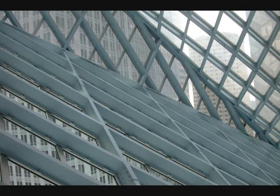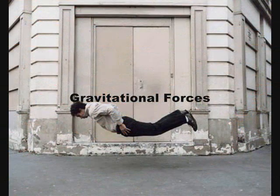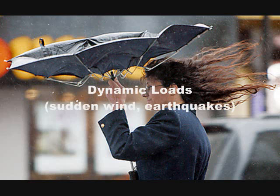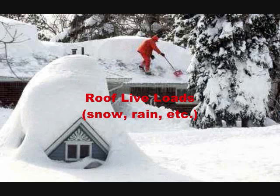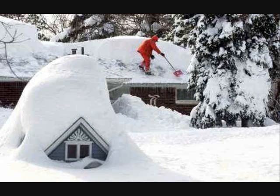As we mentioned before, nodes are where all the forces are redistributed. And there are many forces acting on the buildings, so nodes have a lot of work to do. For example, there are gravitational forces, dynamic loads, which are sudden gusts of wind or an earthquake, dead loads, which are the weight of the walls, the floors, the roofs, and any permanent surface equipment. And there are live loads, which are the weight of the people, furniture, or anything that is movable. And roof live loads, which are snow, rain, etc. So basically, these nodes are responsible for redistributing a lot of forces.